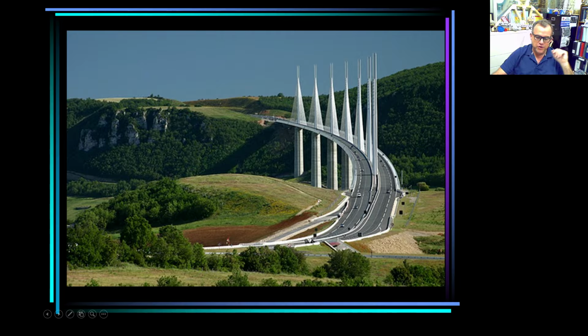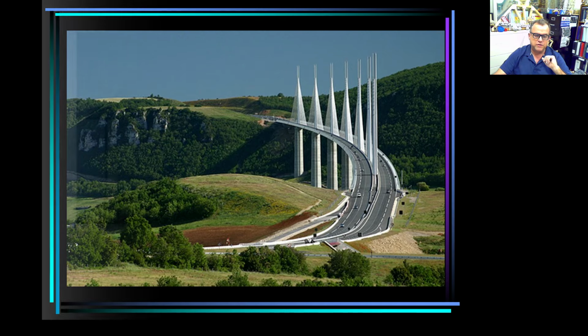Now, where are the supports here? Once again, as the majority of the answers in engineering, the answer is it depends. It depends on what you are studying, what you're trying to do. For example, I know there is a support here holding those girders in the terrain, as well as somewhere here. But on top of that, the supports of the piers are also supports. And the cables are also supporting part of the structure. So depending on what you are doing, you identify different types of supports for different parts of the structure, for the different types of free body diagrams that you can create in those structures.